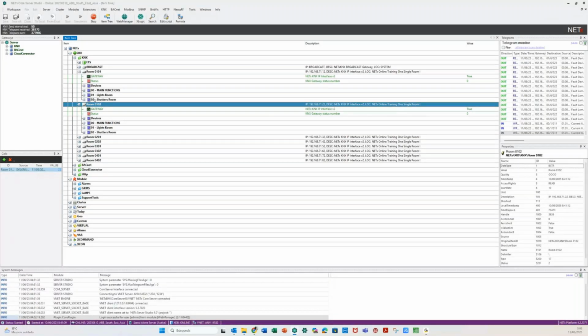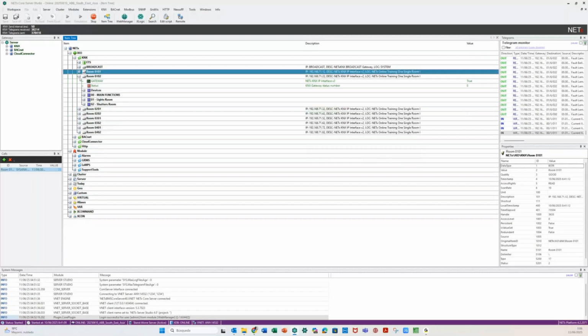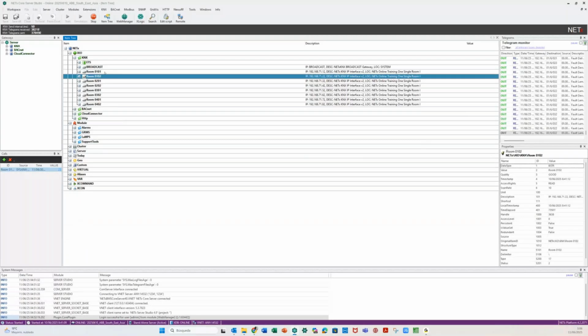So this was the first approach to organize these items in the proper way, because as we are going to see today, this structure or organization is very important. It's very important to save time in terms of planning and commissioning of this BMS. The first approach was to create a small project, but implement it 8 times in our KNX driver here in our BMS Core Studio. That was the tool that we saw yesterday.